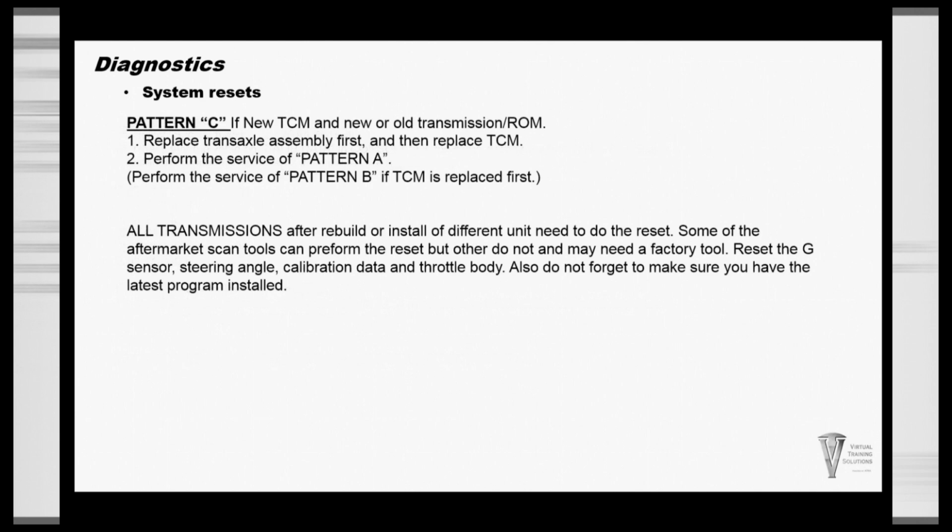Pattern C, new TCM and new or old transmission ROM. So basically what this is saying, it says replace the transaxle first, then replace the TCM. If you have any issues where A and B didn't work, they want you to basically perform patterns A and B again.